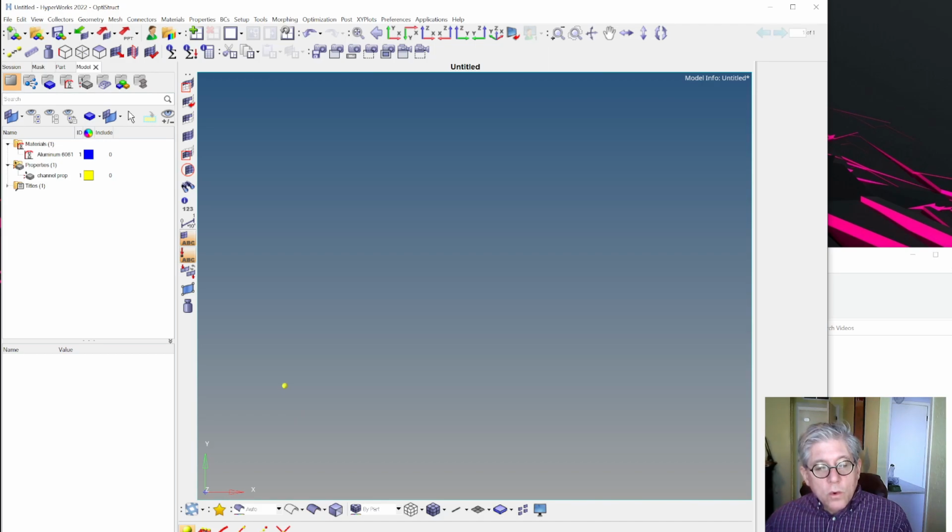And now we'll make it so that the z-axis is the torsional axis, right? So the next node would be at 0, 0, 10, if you will. Okay, and I'll create that. And I think it's off the screen. It's somewhere. Where? Oh, I know why it is. I have to rotate it so you can see it. So if I rotate the axes a little bit. There they are. Okay, so here's the z-axis, right? Okay, so now we're pretty much ready to make the element.